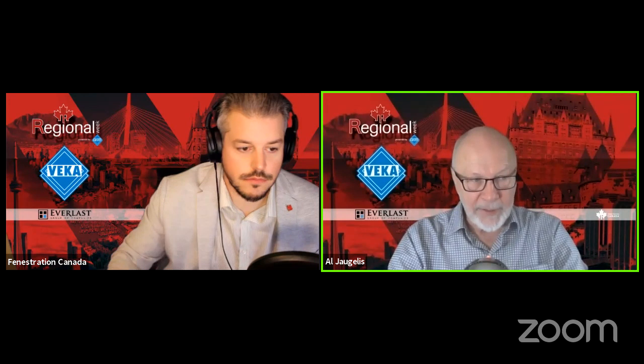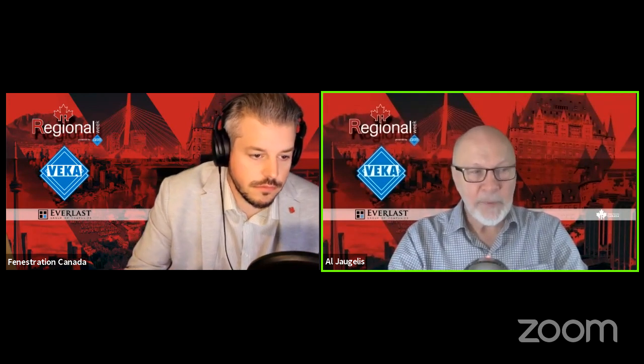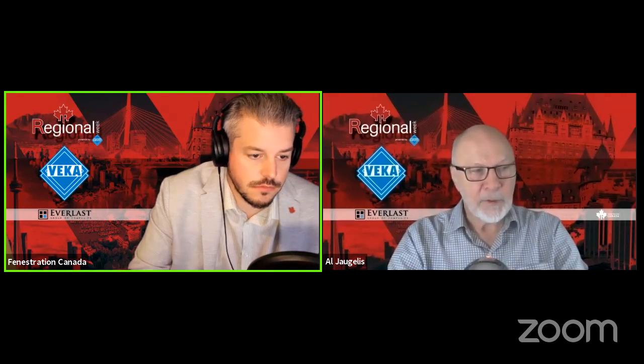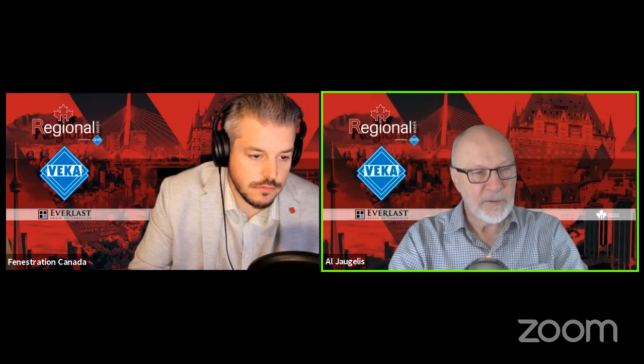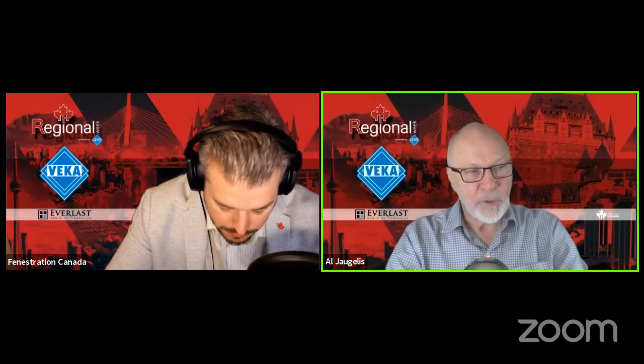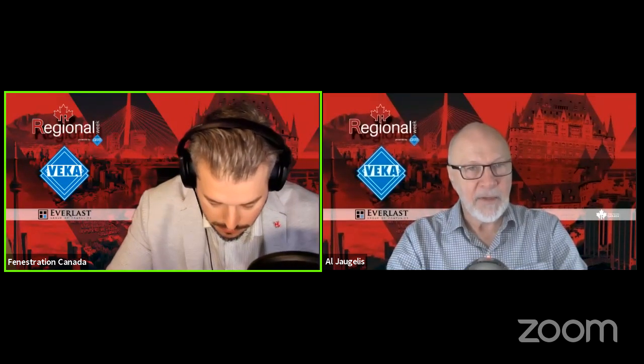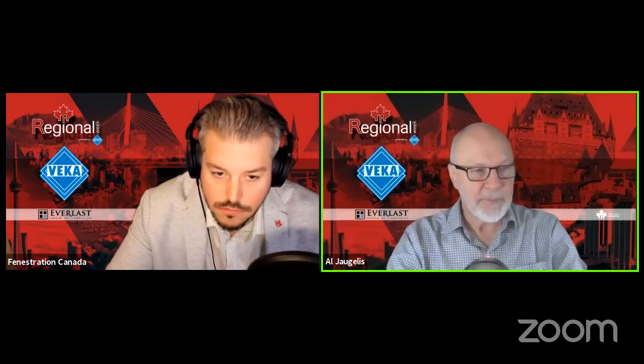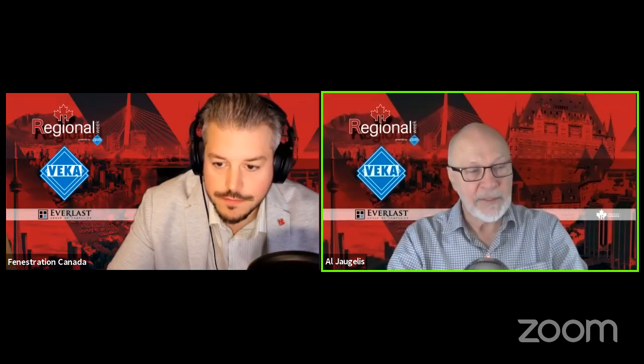The new one is actually more accurate. In some areas, in small buildings, the new calculator actually has reduced pressures from the old calculator. But on large buildings, the old calculator wasn't doing as good a job. So that was an issue with the Canadian supplement to NAFS where the formulas needed to be adjusted. So if you could just send an email maybe to remind me to look into that, we can address that question, because you're right, it might be time to remove the old calculator.